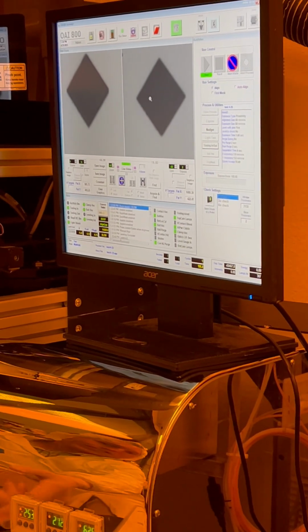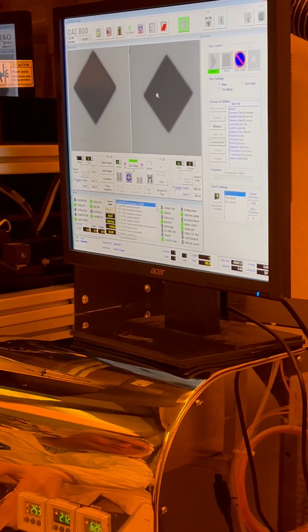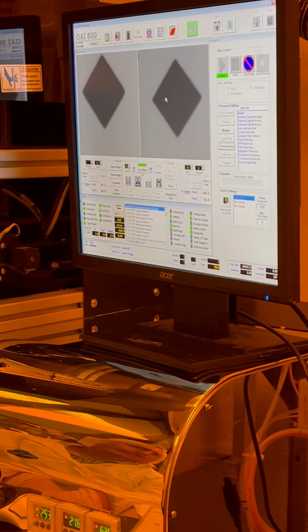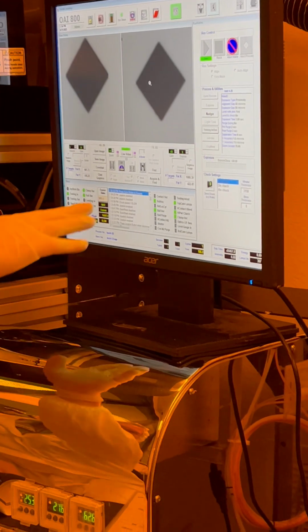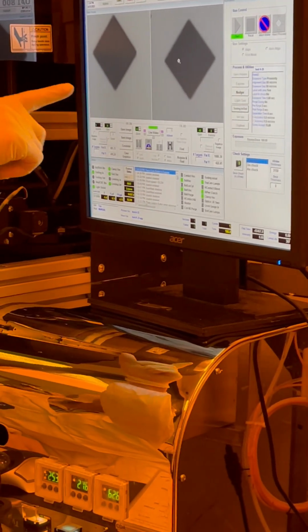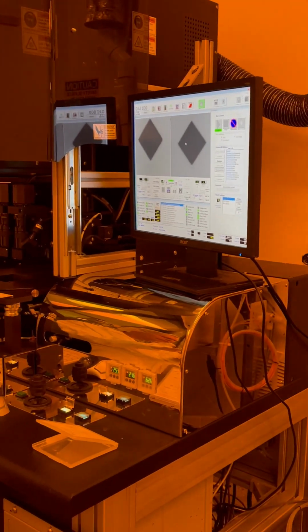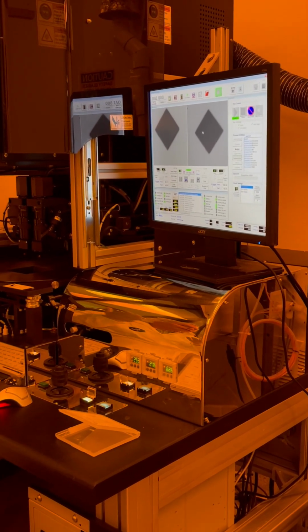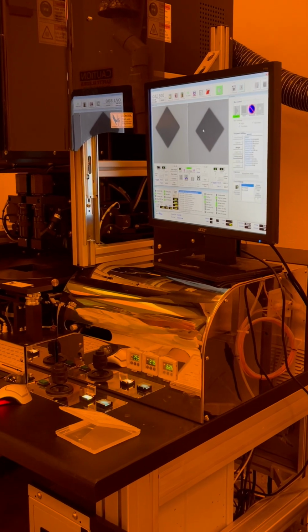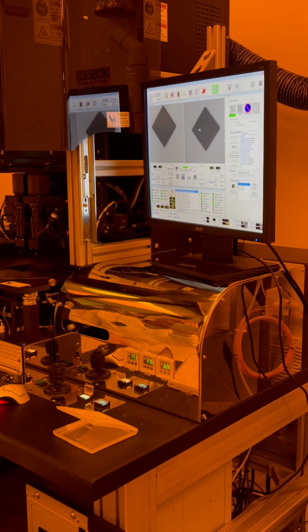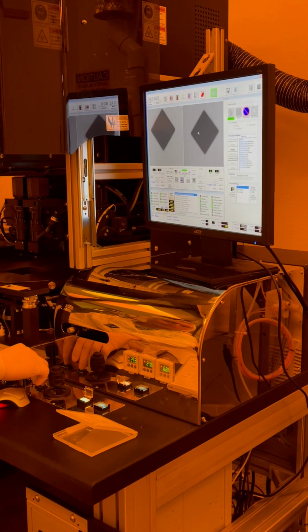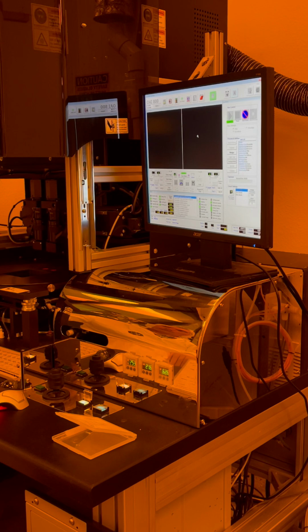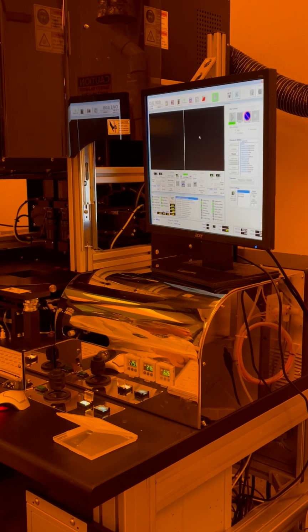Once you get this aligned, you press the button on the chuck, and it says press cycle to expose. When you press that button, it moves from your alignment gap to your exposure gap, whatever your process is. Now if you like it, you can press the cycle button. If I press the button here, it moves those out of the way, and it's going to turn that.